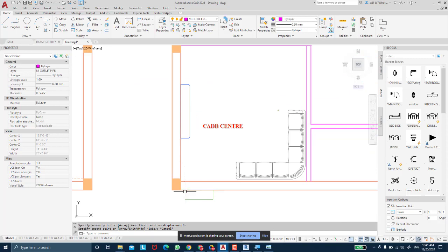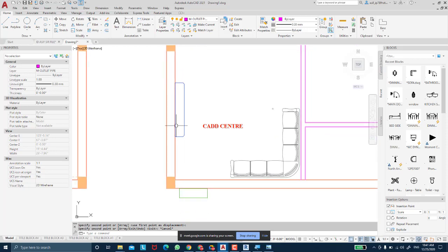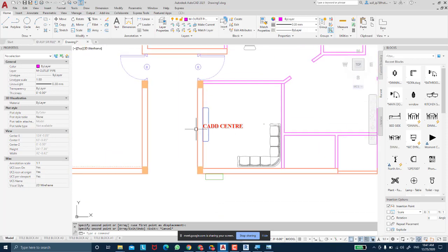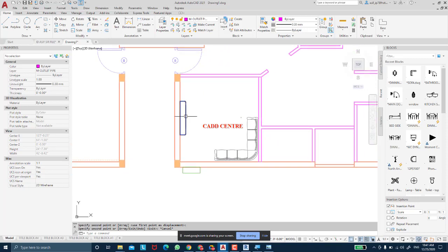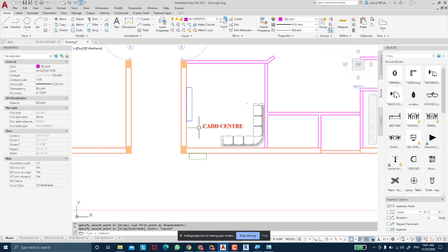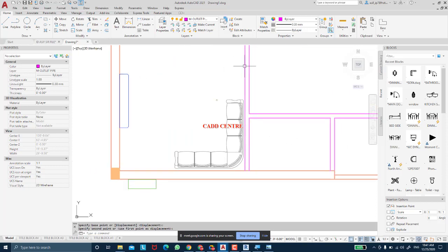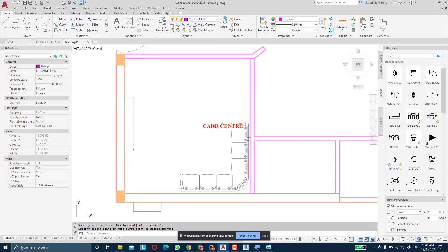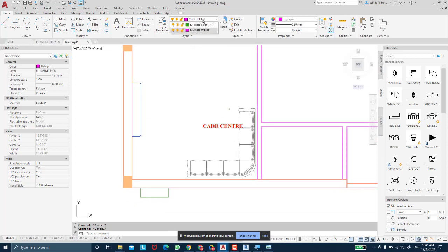So now the copper piping would be coming in and going in over here, and for the outlet pipe, there's no way that we can drop it over here in this bathroom, so it would be a very long pipe. Rather, we can drop it right over here only. And if you want to drop it in this bathroom, you need to shift the air condition maybe to this wall over here rather than on the front-facing wall. Okay, so we're going to make the copper pipe.